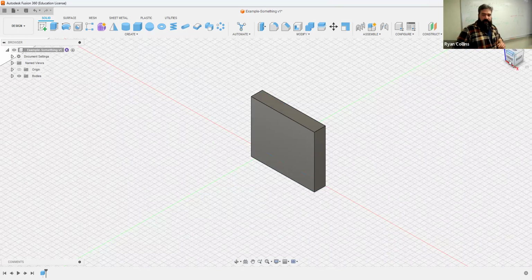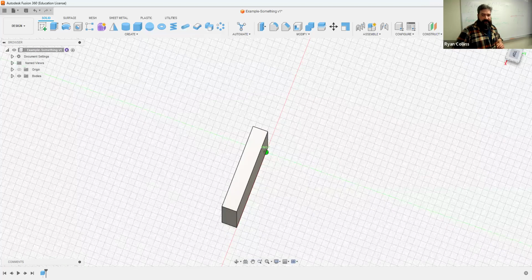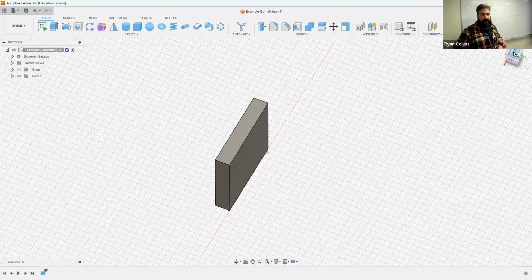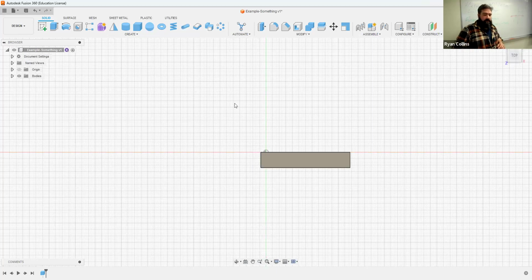So two major ways of moving around and looking at your project. On the top right-hand corner, you have this view cube. View cube has a home button. You can click, hold, and drag on that cube and tumble it around, and you can see the relative X, Y, and Z axes there. So that's why we went over that stuff. Or you can just click directly on any one thing. If you need to rotate the whole project, as you mouse over the view cube, you will see the arrows show up, and you can click that.